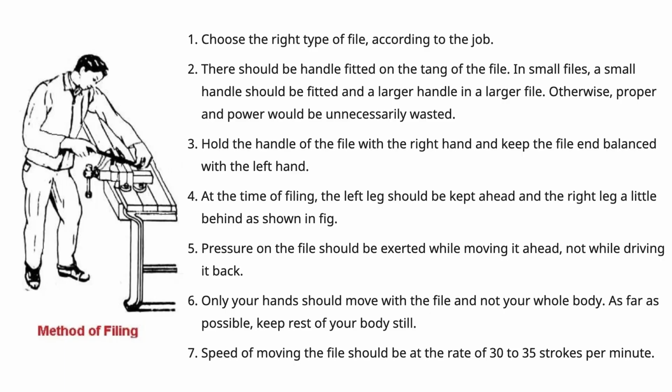The pressure on the file should be exerted while moving it ahead, not while driving it back. That is the way you do it when you go in front. Only your hand should be moving with the file and not your whole body as far as possible. Keep the rest of your body still. There should be little isolated movements of the shoulder and upper extremity compared to the whole body. The speed of moving the file should be at the rate of 30 to 35 strokes per minute. The fewer strokes you need, the better you can do. That comes with expertise.